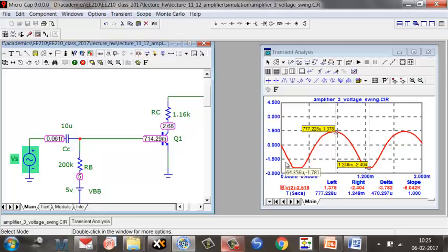Okay? So the other thing that you must be seeing here is that on the negative side, I'm able to reach almost very close to the value. Minus 2.5 is the ideal. That's what you could have gotten, right? If this is 2.5, the output swing would have gone to minus 2.5. On the positive side, you're not able to go to 2.5 at all. Okay. All right.